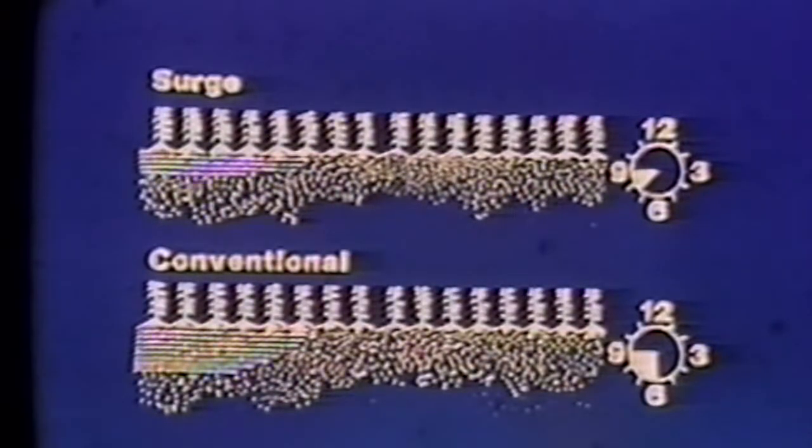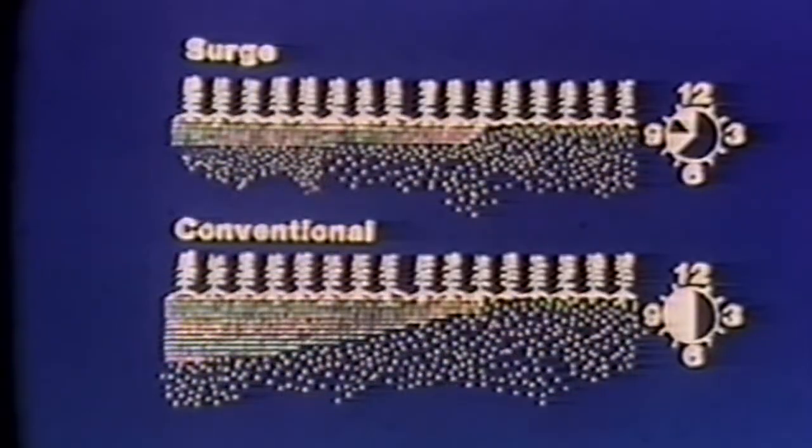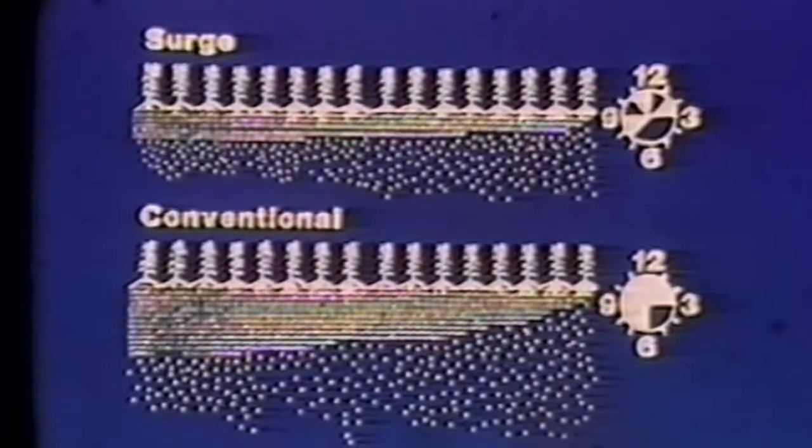General experience has been that the same stream size will advance down both sets of furrows using surge in nearly the same amount of time it takes the conventional method on one set of furrows, or advance down twice as many furrows with the same amount of water. The result is less deep percolation toward the upper end of the field. The reason for the surge effect is not fully understood, except experience shows that each time water is returned to the furrow, it flows rapidly down the previous wetted furrow at a much faster rate.